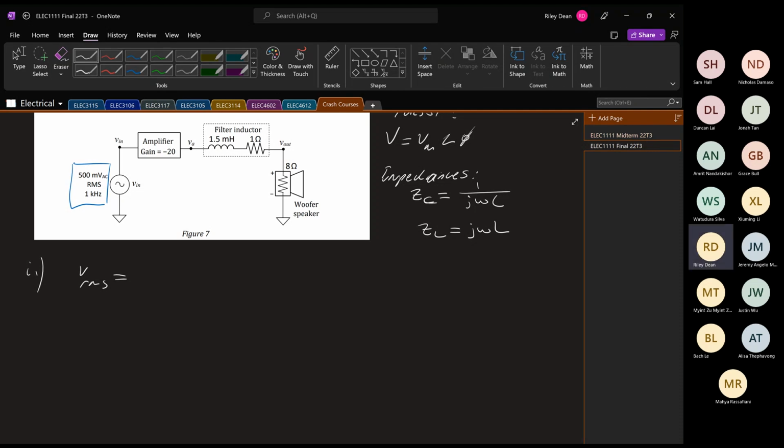Basically, RMS voltage is the AC voltage divided by √2. It's also known as root mean squared. Not that it really matters for us in this course, but it is worth noting that RMS voltage is divided by √2 only for sinusoids. That is just an identity we know through, I believe, an integration.